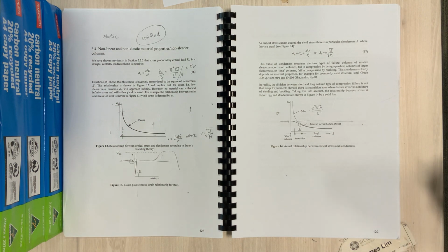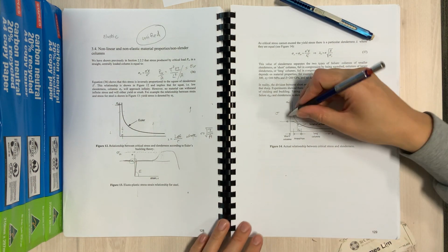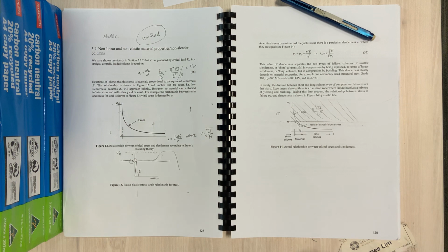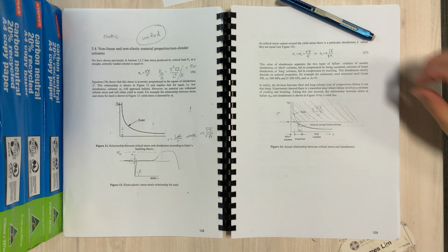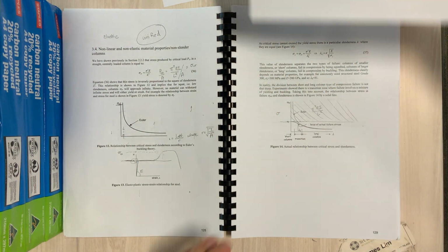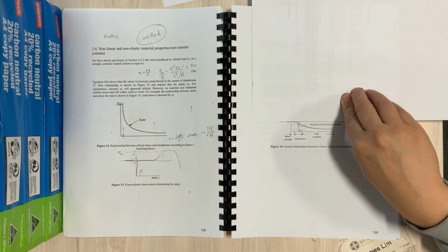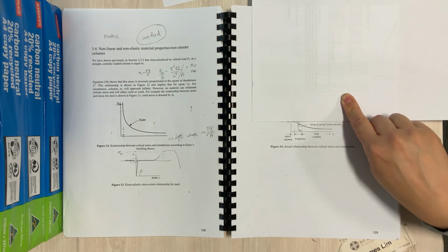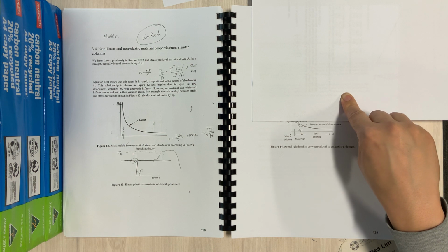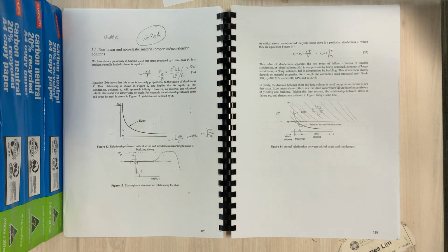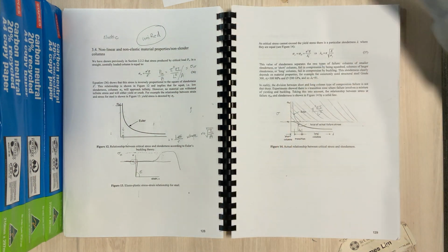Okay, so we're basically saying that your structure or your material cannot take a load higher than the yield stress. So everything above there is effectively redundant. We can forget about that portion of the graph, because we know that your material cannot take that stress. Obviously a short column is going to buckle at a much higher load than a long column, but we're saying the short column is not going to buckle; the material itself cannot take that stress, so it's going to fail. So we can effectively forget about that.